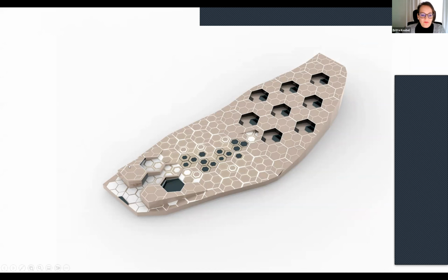On the left, we have the drop-off. There we have some buildings like a restaurant, all-day dining, and reception area. Then we have a swimming pool. Then you walk over the central area, which also has some water elements to cool down, to use evaporative cooling. And on the right side, you see the villas nested in nature. On the left, after you drop off, you also have shading because it's extremely hot. Actually, the wind flows in this direction, so it also helps us. We channel the wind. It goes over the water bodies, and then it blows over the cottages.